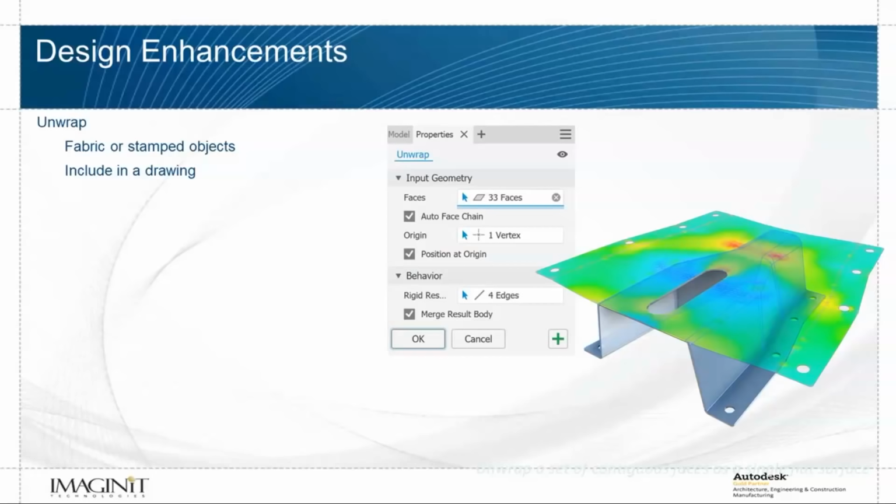as you go through, it's going to give you some information so you can see the areas of tension. That's kind of the heat map that you have. This is not following K-factors. This isn't following unfold rules. This is just kind of giving us a flat pattern. So realistically, I think this would be something very close. If it was a really complex part with all kinds of different bends, in this case, we're getting so little, it's got a little bit of yellow, mostly green, two points of red. I bet this is coming really close.